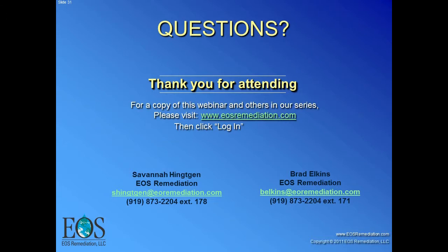So I think the answer is if your plume is already naturally attenuating very effectively, then probably you don't need to enhance it. But if you have a plume, that suggests that something is missing, and our experience is what's missing is electron donor. In some cases it might be pH, it might be bugs, but typically if you've got a plume, you're probably going to need to do something to speed it up.